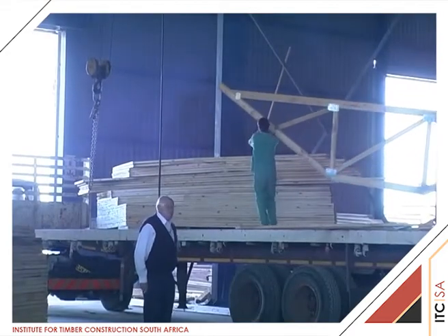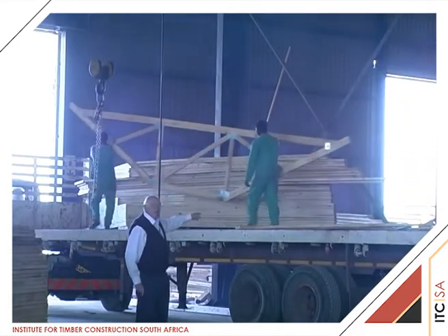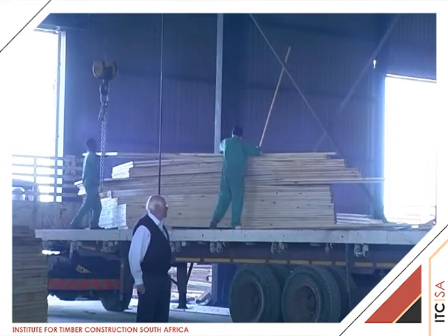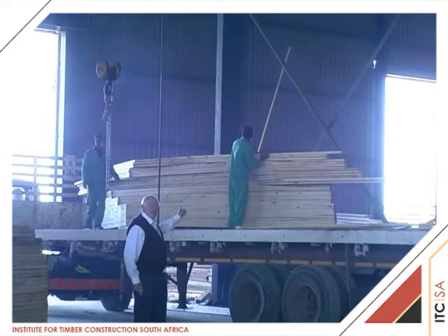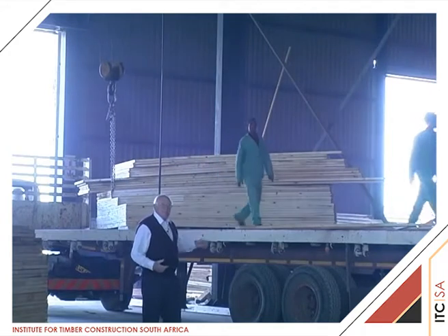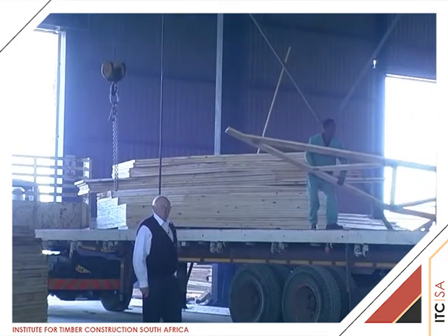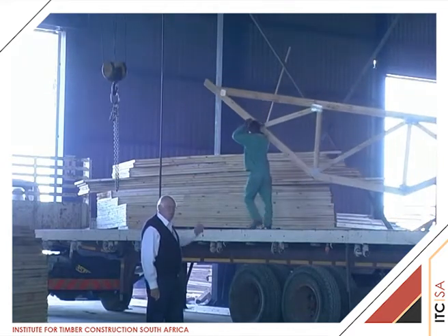The completed trusses are loaded onto trucks, and note how they're being vertically carried. The handling of the trusses is very, very important. They're carefully stacked, they will be tied down, delivered to site complete with the erection and bracing details for offloading on site, careful stacking on the site, and handling according to these requirements.